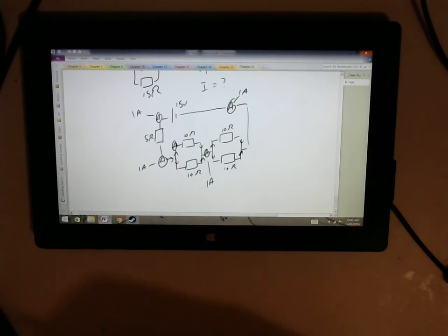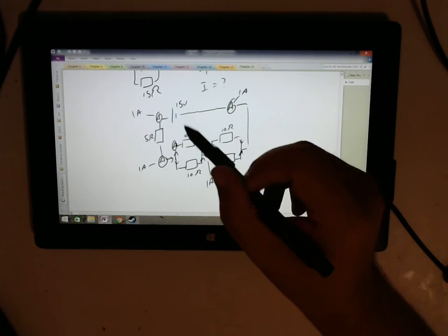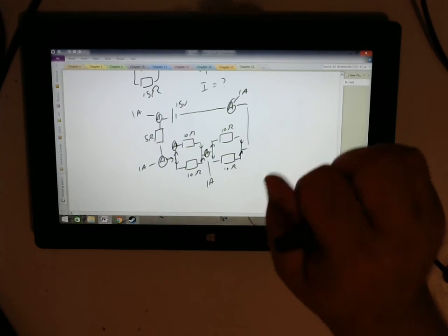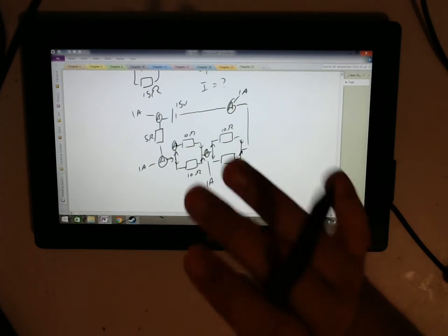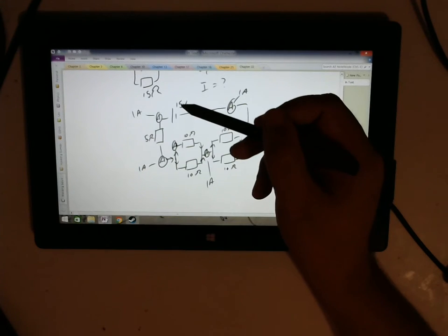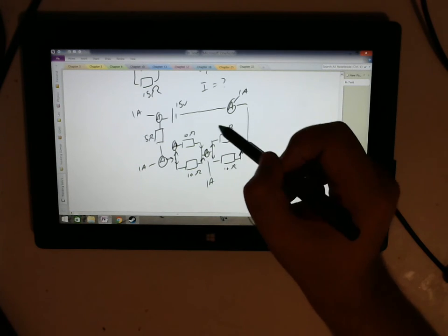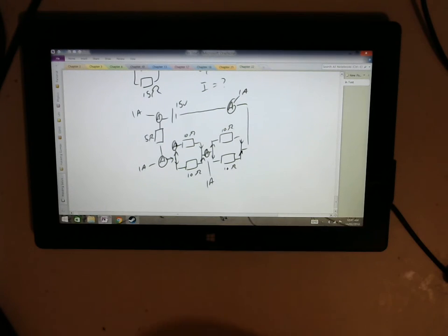Okay, because at this point all the current needs to move together. So if you're uncertain of that, rewind it, listen to what I've just said again. In these sections, the total current we worked out as being 1 amp from those original things: we worked out the equivalent resistance, so that we had just one resistance number to use for the entire circuit. We used that with the voltage to work out the current, I equals V divided by R. And that told us the entire circuit has 1 ampere of current going through it.